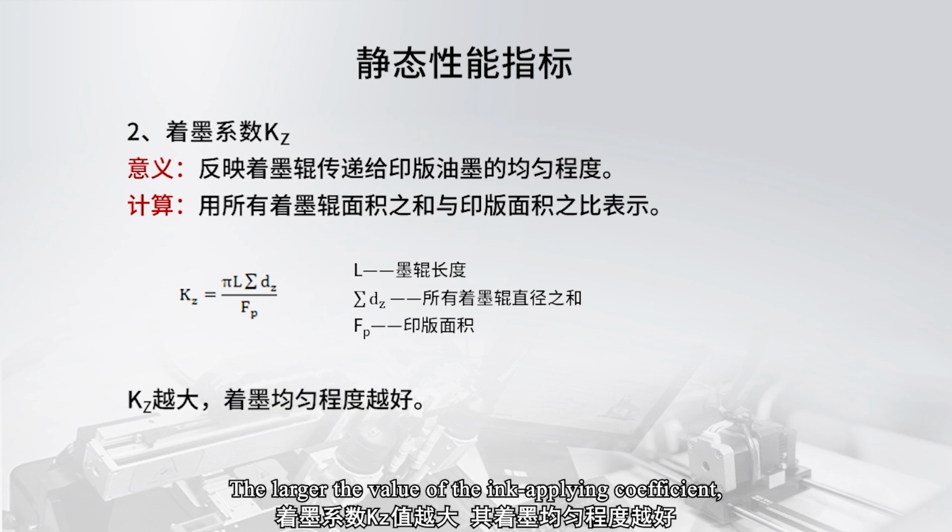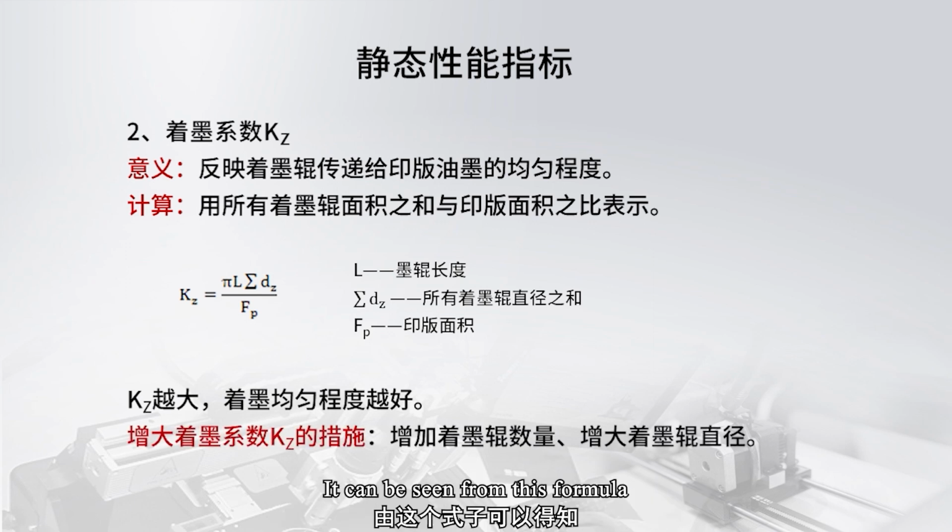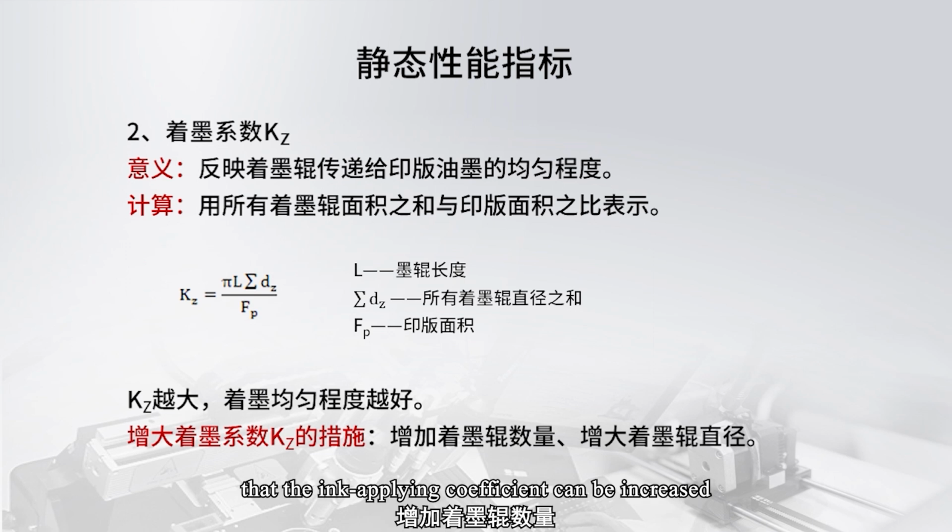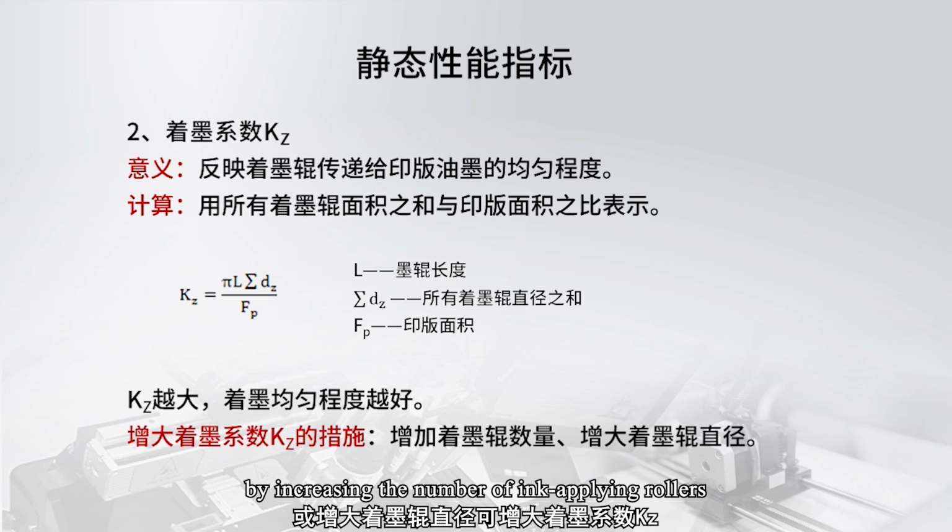The larger the value of the ink applying coefficient, the better the uniformity of ink application. It can be seen from this formula that the ink applying coefficient can be increased by increasing the number of ink applying rollers or the diameter of the ink applying rollers.